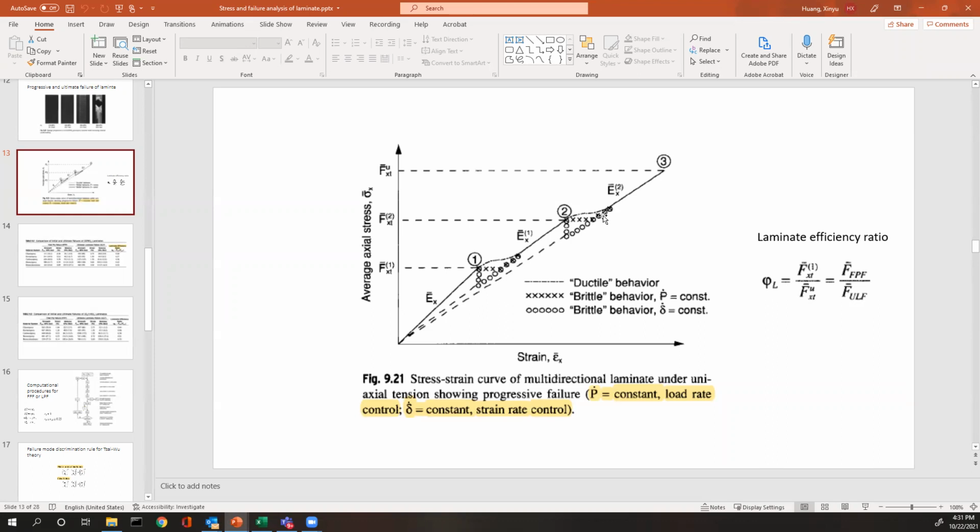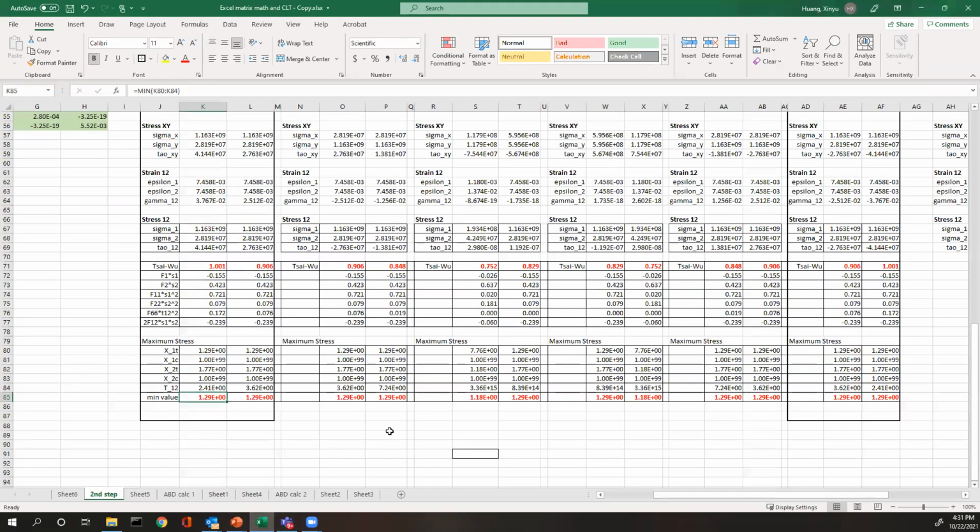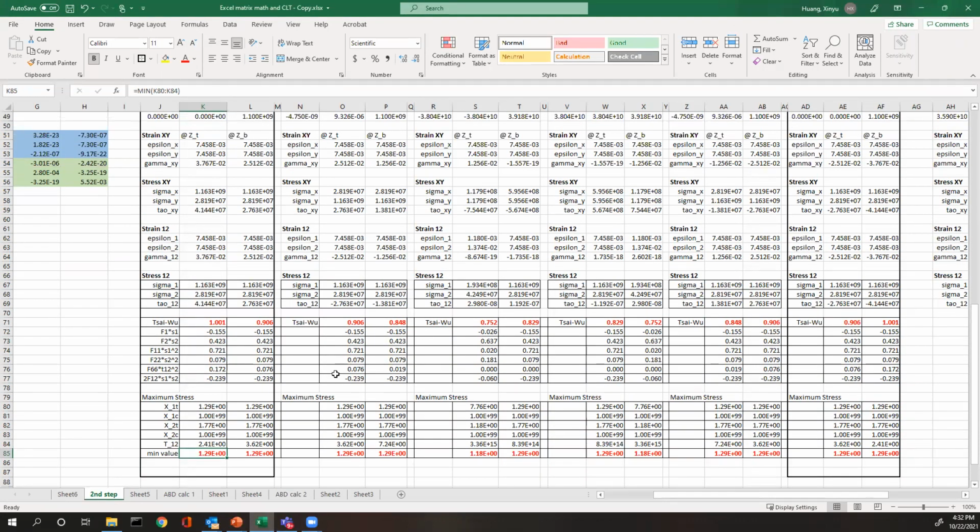If there is a different layout, a different number of layers, the load could keep growing a few more times until it reaches the condition that fibers start to fail. In my case, I just keep updating. If that needs another step, I would save this state, copy and paste into another sheet, and keep calculating until I find another state when a layer fails, and I reduce it.